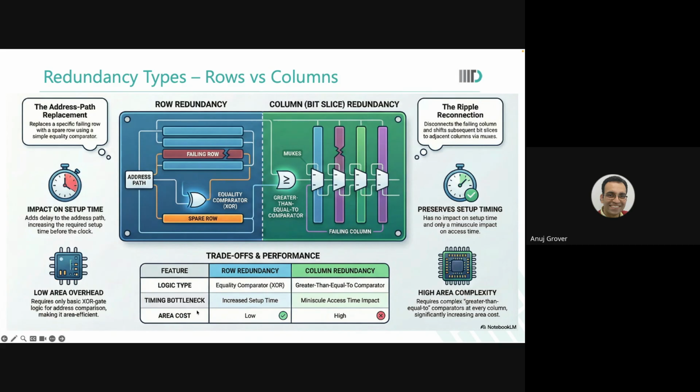This one VR is weak. One contact is weak. What happens? Its resistance goes up to 10K ohms, 30K ohms, 50K ohms, and still at the time of testing it worked. But since it is very high resistance, when you flow X amount of current through it, it will keep on getting heated. I squared R physics. And when it gets heated, this resistance increases. And then, you remember the last lecture in PVD? We talked about failure modes, and we talked about the failure mode called electromigration. What was that about?